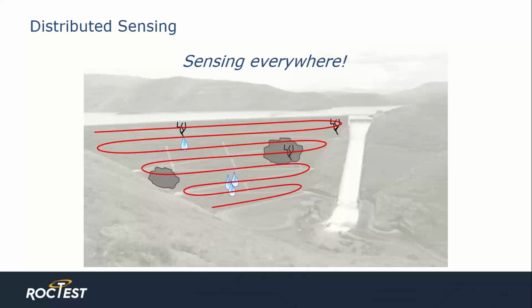In this slide, you'll see very clearly that because the distributed cable itself is the sensor, shown here as the red line, the dam can be completely covered fairly economically. Using distributed temperature and strain sensing, we can monitor for soil deformation using the strain data and for leak detection using the changes in temperature data, both with a spatial resolution of 1 meter.